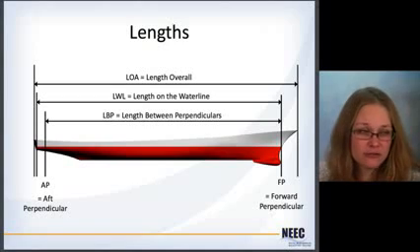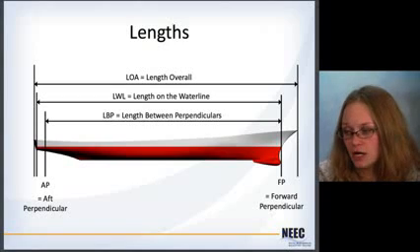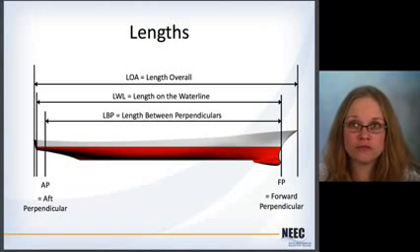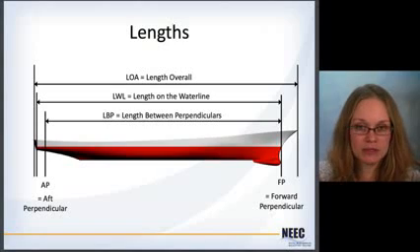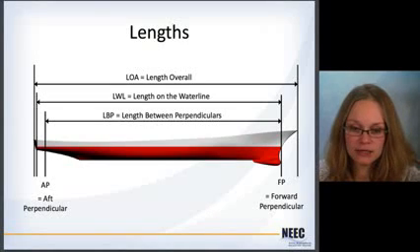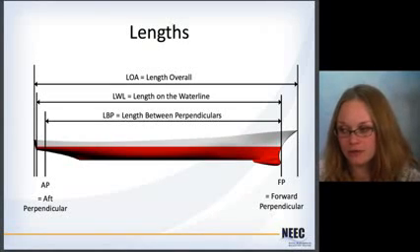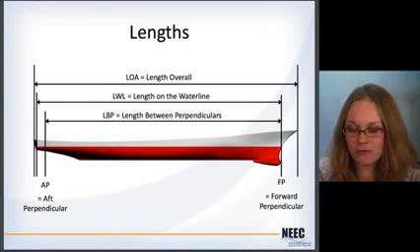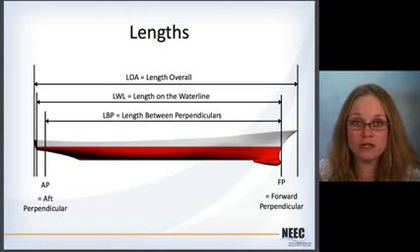Okay, so there are several different lengths that we end up using when we talk about ships. There's an overall length, which is very important when you're looking at how much dock length I need to actually bring my ship up to a dock, right? You've got to make sure you have room enough for the entire ship. But when you're looking at how the ship is going to behave in the water, you often don't really care about the part that's above the water because it's not going to have much of an influence. You're looking at the part of the hull that's underneath the water.